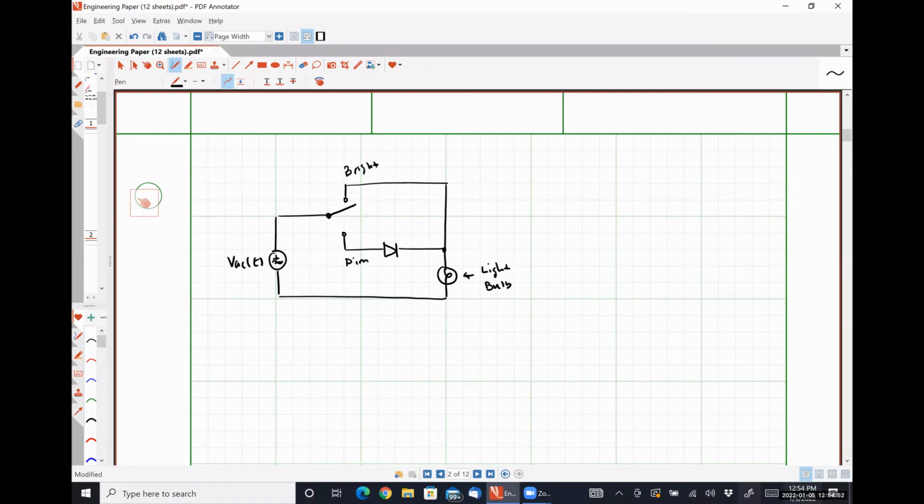Those two things are what the forward bias current of the diode is going to be. So we need to know what the maximum diode current will be for our given load. Obviously, if the diode is expected to draw too much current, then it'll fail, right? And it can fail open, meaning that it's always going to be an open circuit and never conducts again, or it can fail closed, which means it's going to look effectively like a short circuit. And so we lose that rectification, or we lose that partially conducting and partially not conducting response, okay?